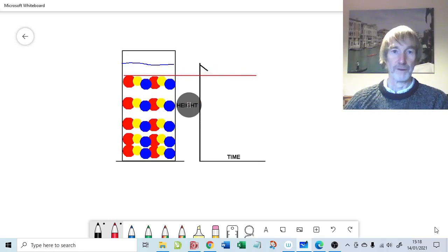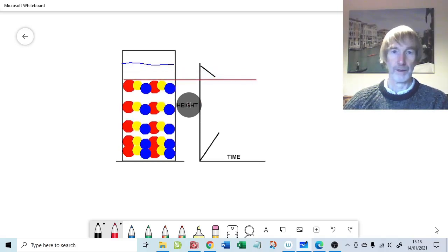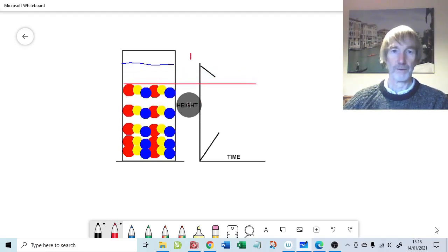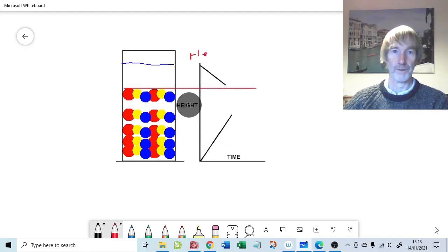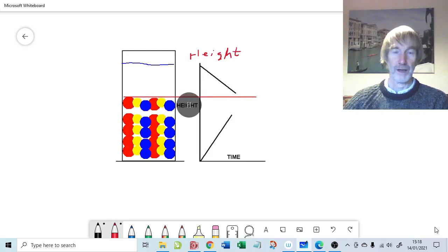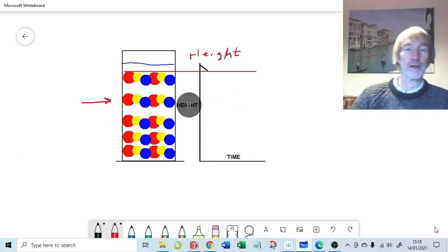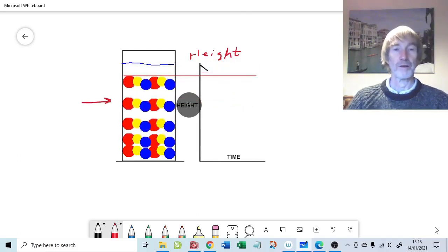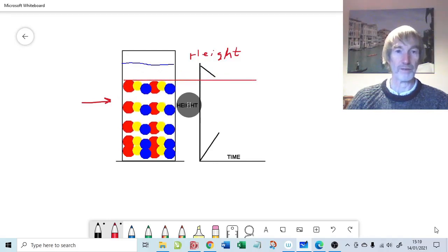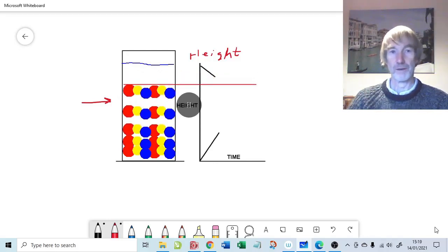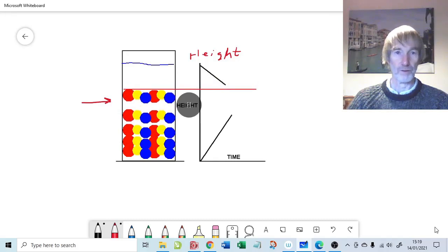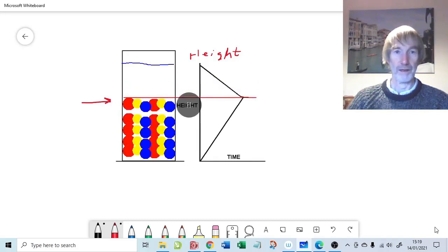So what we have here is the height of the interface. Okay, and there's a clear visible interface. It's just about here. Just jump back up to the top, and you can see the particles are in hindered settling. The particles are getting in the way of each other, and it's settling en masse. And we can see the interface has just made it to my arrow roundabout now.